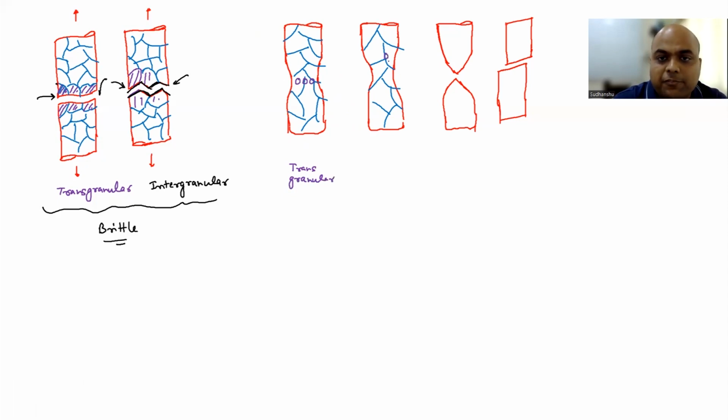Here, the voids are forming in case 2 along the grain boundaries. So this is a typical case of intergranular. Okay. And these are related to plastic growth of voids. Again, we will discuss why voids are forming and where they should form when we talk about ductile failure.